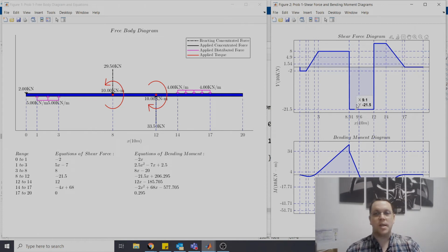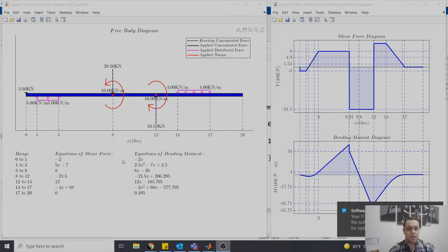I don't want you to just say that they changed. Talk about things like the magnitude. So why is it so much higher now, or in this case lower, to have the shear force at these 2 points different? Think about what's actually happening. You're now supporting it at the point where you're torquing the loads, and things like equations change for this.